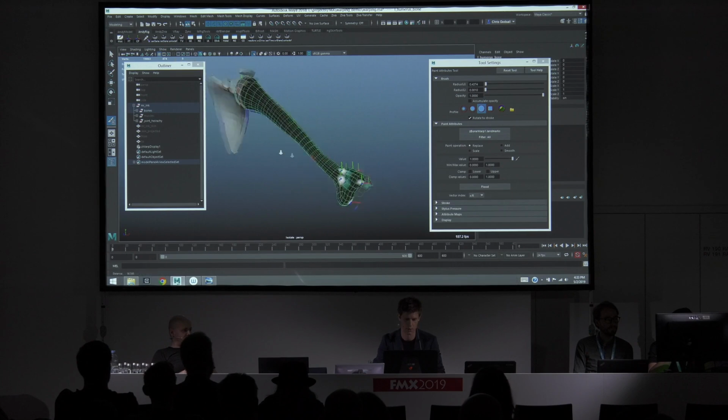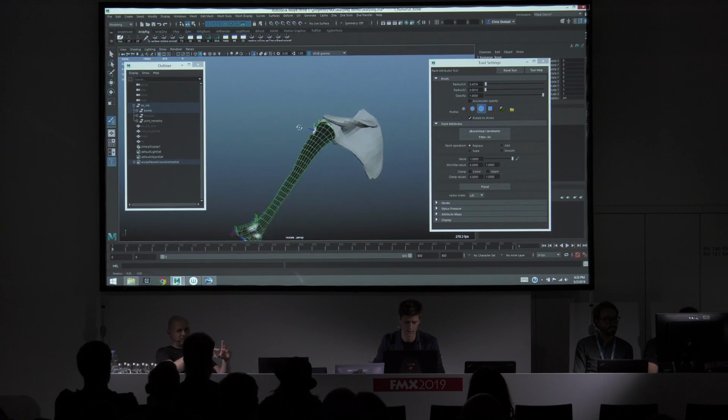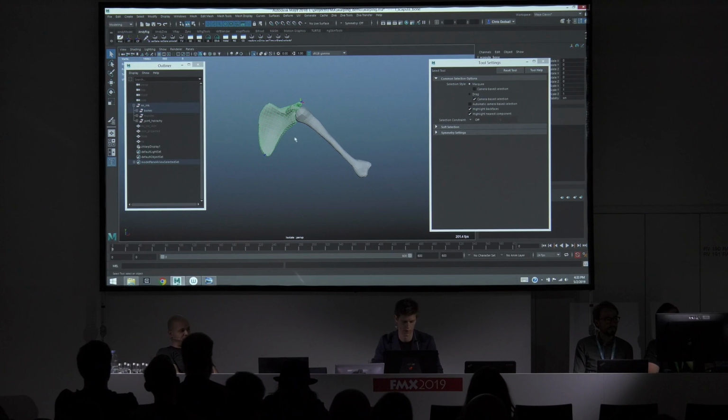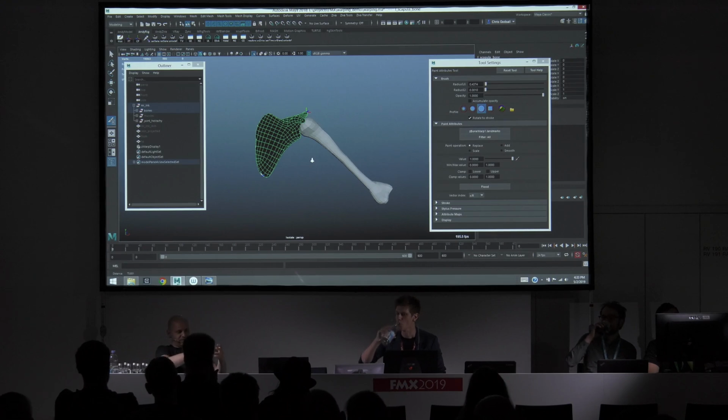The other thing to know with the way the landmarks are generated, when you paint an island, like so, if you painted a splotch which included 10 vertices, the landmark will be centered in the center of all those points. So that's useful, like say at the head of a bone, if you want the landmark to be right in the middle of the head, you'd paint the entire head of the bone. It will put one landmark in the middle of it.